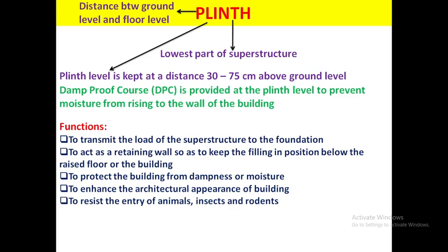Functions of plinth: to transmit the load of the superstructure to the foundation, to act as a retaining wall so as to keep the filling in position below the raised floor of the building, to protect the building from dampness or moisture, to enhance the architectural appearance of the building, and to resist the entry of animals, insects and rodents.